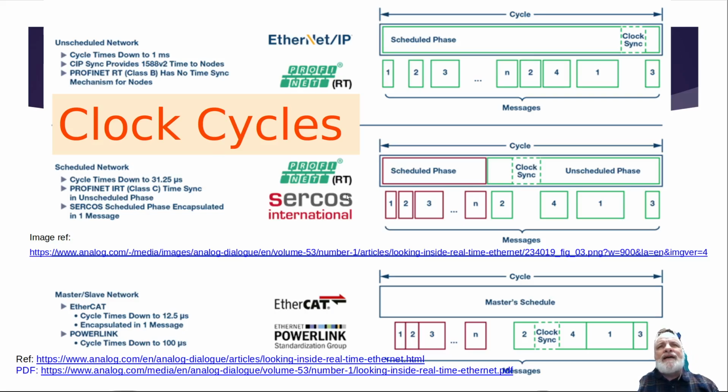And then there's the Sercos down here, which requires some different physical hardware, and also the EtherCAT that I mentioned. The difference here is that the clock signal is at the lower level, so you actually can't use a standard switch for something like EtherCAT. You can't just go out and buy an ordinary switch like you could with Ethernet/IP. You have to have a switch that has been designed to handle this clock signal and this real-time guarantee that the data is going to get through.